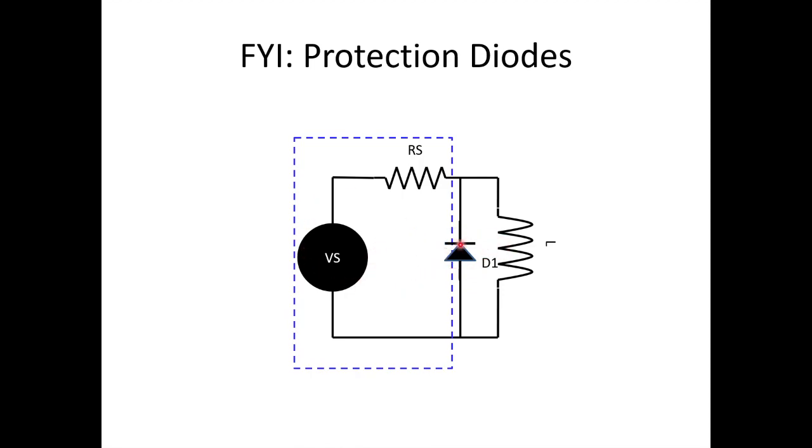Now, this is only one methodology. There's lots of other different diode protection schemes out there. I'm only showing you one here just as an example, that diode protection schemes are probably the most popular. And sometimes they'll even have back-to-back Zener diodes here. There's lots of other variations on the protection schemes to protect your active circuits against inductive kick.